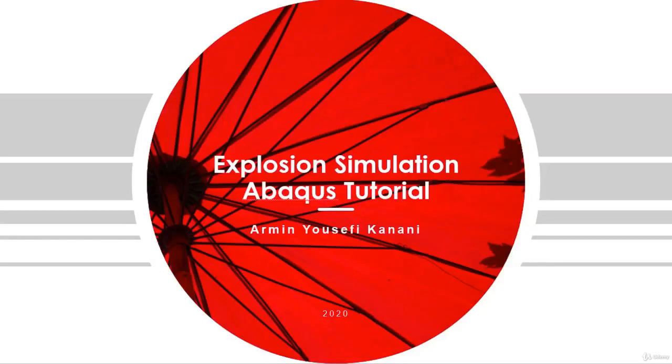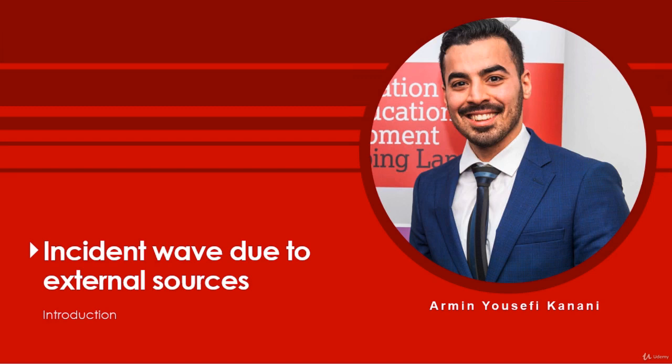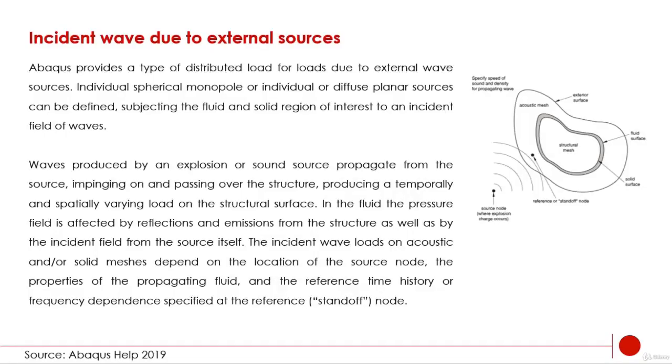Hello everyone, in this video I'm going to give you some background information about an incident wave due to external sources. Abaqus provides a type of distributed load for loads due to external wave sources. Individual spherical monopole or diffuse planar sources can be defined, subjecting the fluid and solid region of interest to incident field waves.